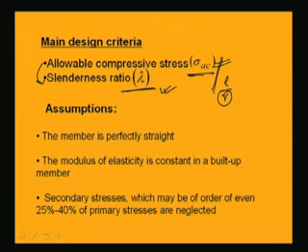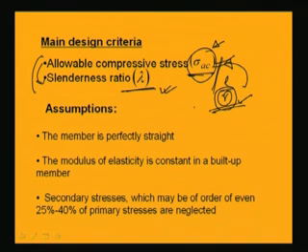So it is an iterative process, because we do not know the allowable compressive stress and we do not know the dimension of the column, so we cannot find it out straightforward. Either we have to assume some allowable compressive stress, on the basis of which we can find some approximate dimension of the member, and then find the actual compressive stress coming on that particular member. Otherwise, we can assume some member. With this basis we have to design, that is why this is called an iterative process.